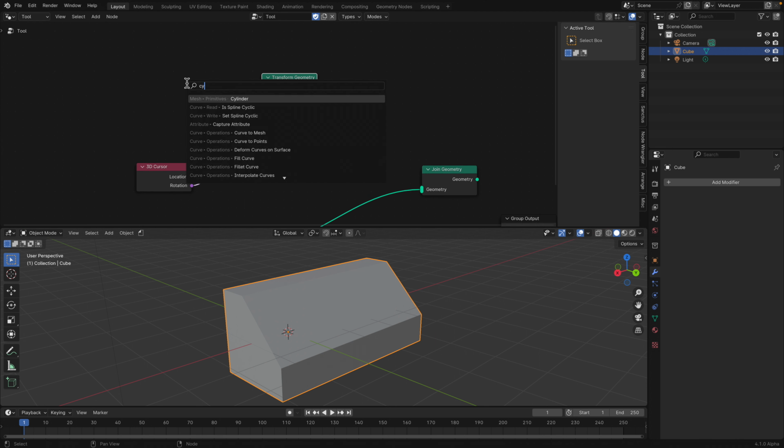But I think the advantage with the grease pencil is you can draw in 3D space in object mode, and then the modifier will be added in the object mode. So let me restart Blender 4.1, back to the cursor. By juggling the 3D cursor, shift right click will actually place the 3D cursor where it lands on the surface, like that. And at that very point we can bring in anything through the tool.